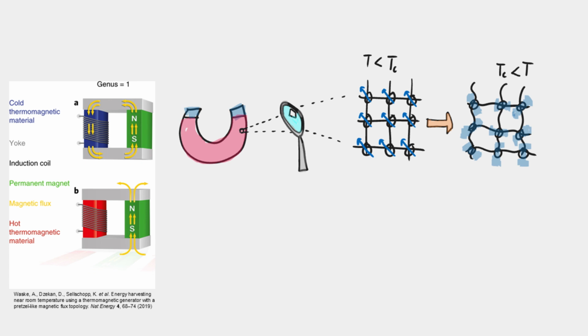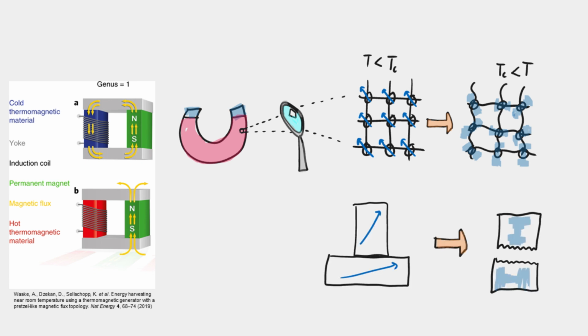As an example, the change of the magnetic phase may be tied to the change of the shape of the structural unit cell. This instability in the structure may lead to a rapid change in the overall magnetization, which can be nice for generating electrical energy, but can be a challenge for the longevity of the material in operation.